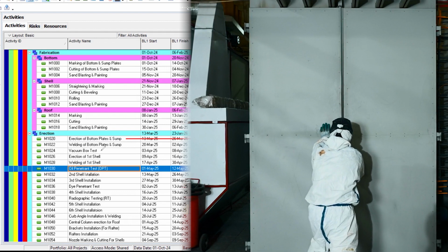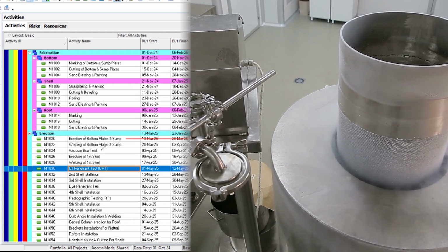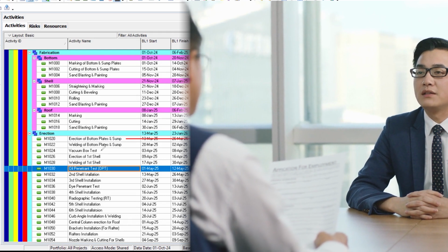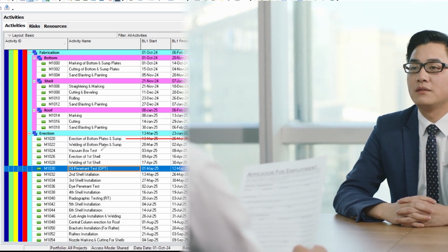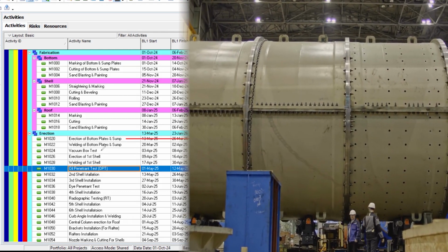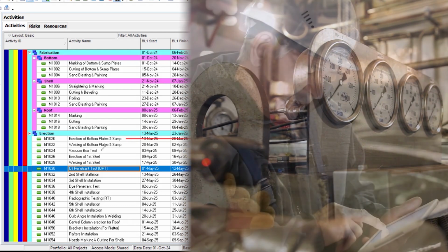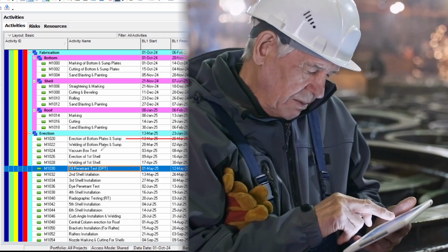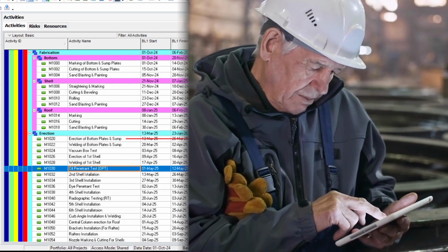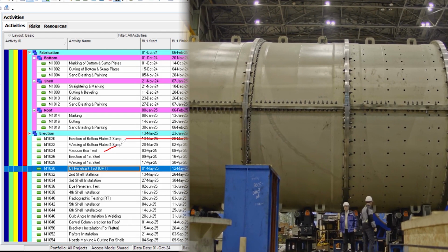So as a planning engineer, you should understand this QA/QC requirement as well, and the definition, because when you go through such job interviews, having learned planning engineering using Primavera P6, sequencing is one thing, but another thing is to know such tests. So the vacuum box test is used to find out if there are any leaks and so on, right? Then once the bottom plate erection on the foundation area is done, welding is done, and the test is done.